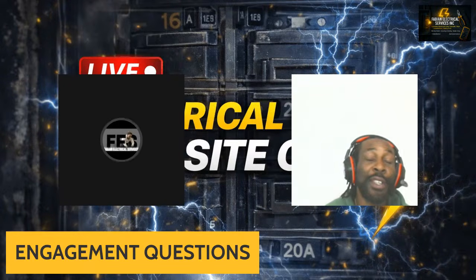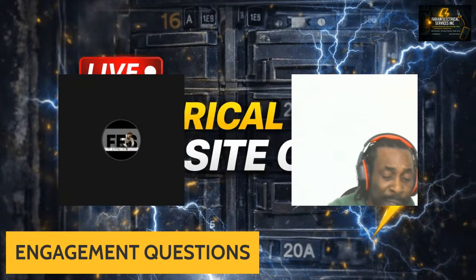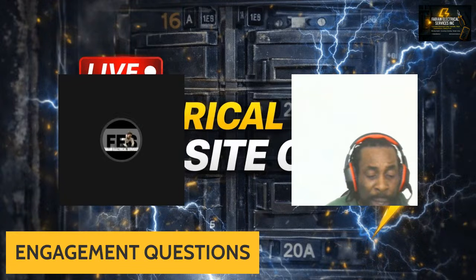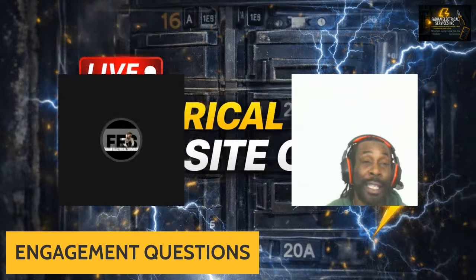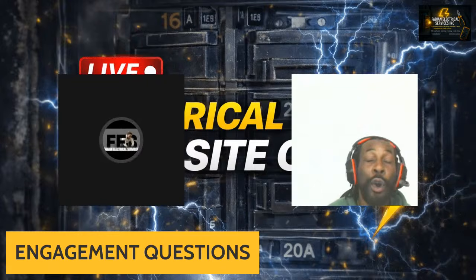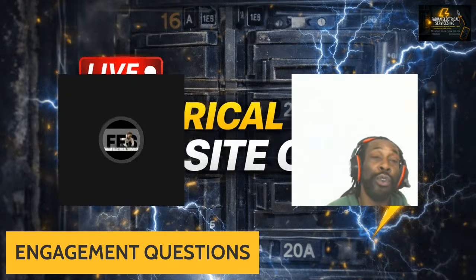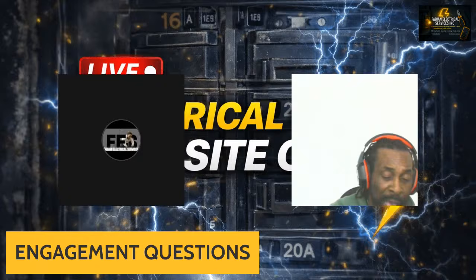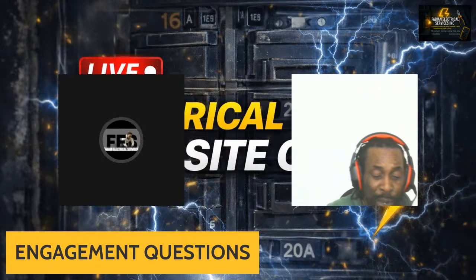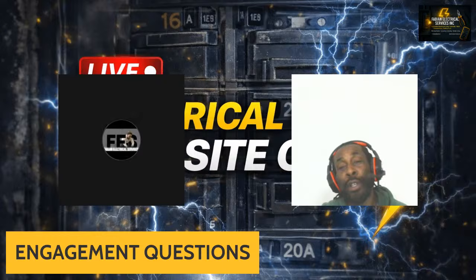It creates dirty power. Dirty power basically happens when you're over your 80% rule. That's when you have the unbalanced neutral, where you have your dirty power coming back. So again, it's very important to keep that in mind.